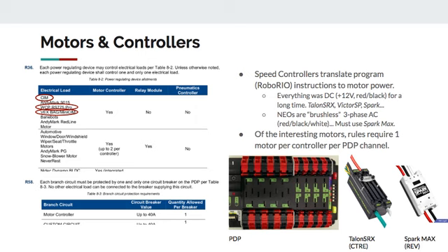You have to have a really fancy controller to make sure the electronic signal is going at exactly the right time. And so that's why the Spark Max, made by Rev to go with the Neo motors, comes with these 3 wires on the output. They're basically the same size and have almost the same connections. We just have to make sure we wire the correct one up. Cool.